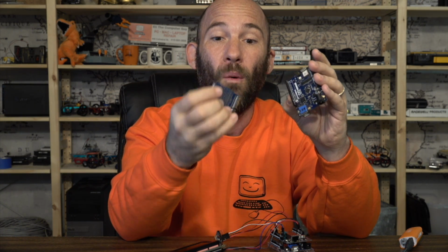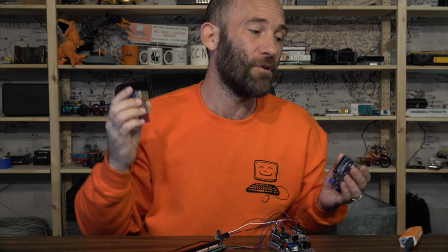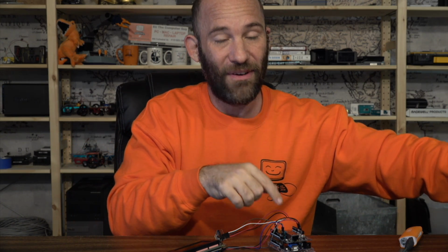ICSP headers. Well, the problem is the data logging shield that I personally really like. This is a Adafruit data logging shield. Works well for many other projects. I was literally just using this for my Arduino projects, but for some reason, since this does not have those ICSP headers, the Arduino Uno with Wi-Fi doesn't like to play nicely with this. So if you're going to be using some kind of SD shield with your Arduino Uno with Wi-Fi, it's going to have to have those ICSP headers in order to make it work.